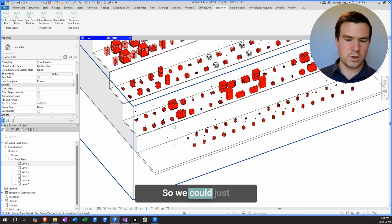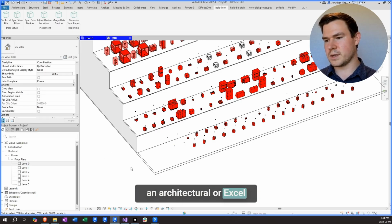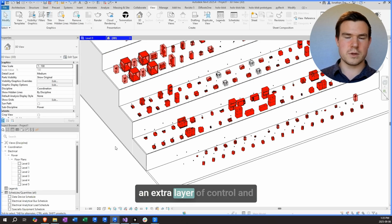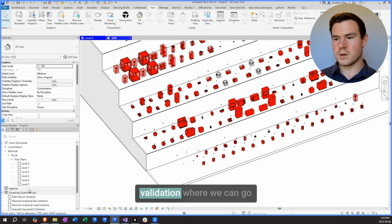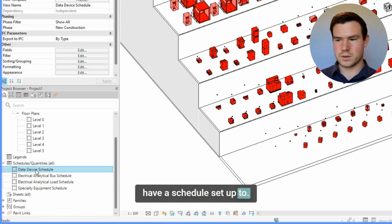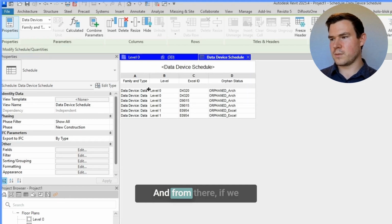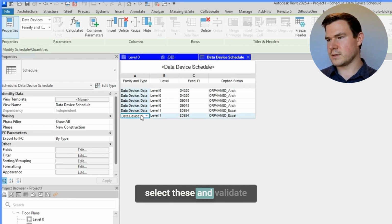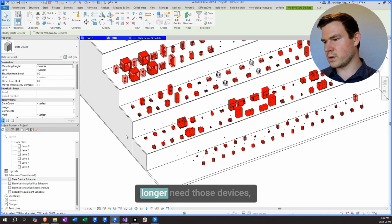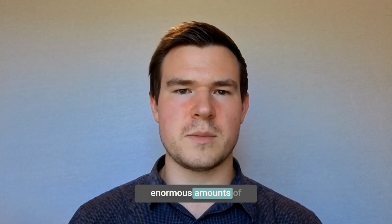So we could just automatically delete any elements that no longer have an architectural or Excel match, but we're just adding an extra layer of control and validation where we can go into our schedules, and we have a schedule set up to isolate elements that have an orphan status. And from there, if we select these and validate for ourselves that we no longer need those devices, we can just delete them. Tools like this are eliminating enormous amounts of repetitive and error-prone work for our partners.